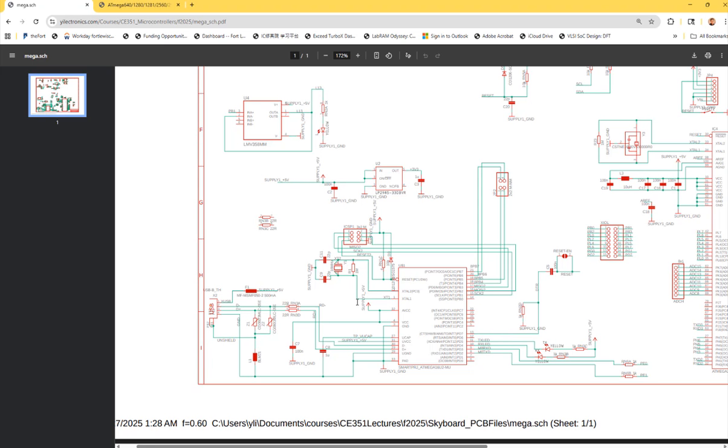Or if you want to use a regulator, which is a lot of times used in a product, we usually encourage students to use a battery power supply with a voltage regulator on it. That's another very good practice in the future. I mean, a lot of times the interviews will ask you the questions. I mean, what's the voltage? How to supply the voltage, right? So this is a fundamental thing you guys need to learn actually.